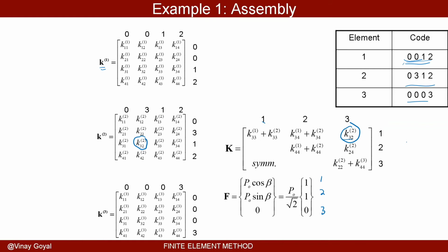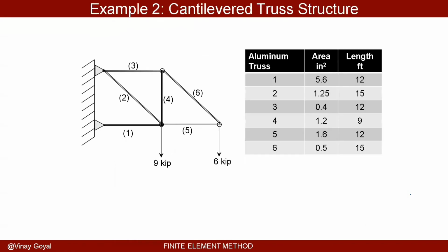Now that I have the stiffness matrix and force vector, I'm primed, because remember that F equals K times D. And I'll use the convention in my book with the underscript. I can solve for the deflections D by inverting the stiffness matrix and multiplying by the force vector. These are vectors according to my book. So I can calculate deflections, and once I know deflections, I'm ready to go. I have been successful. Very, very nice. Very powerful, and very exciting.